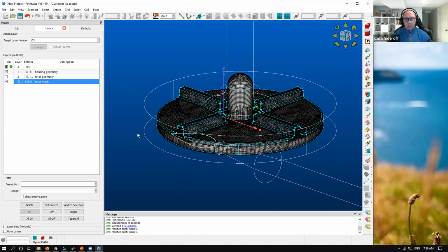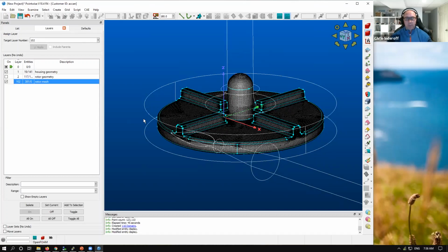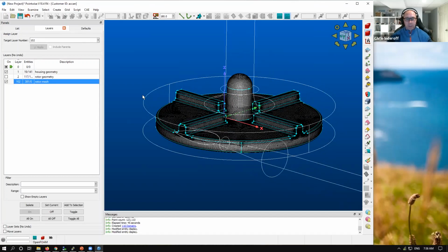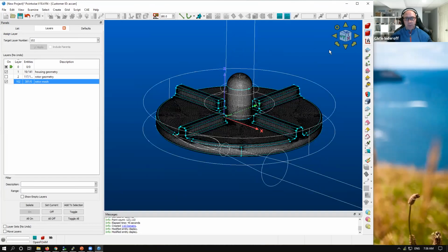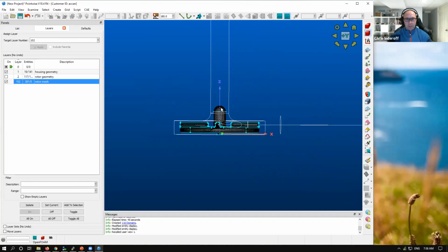We can either do it with a moving reference frame model where we just apply the source term into the steady state system of equations, or we can actually dynamically rotate the model. Either of those approaches, we're going to need to create another region for the rotor where it moves. So I'm going to split up, not chop up, that's a bad word, the housing geometry to accommodate that.